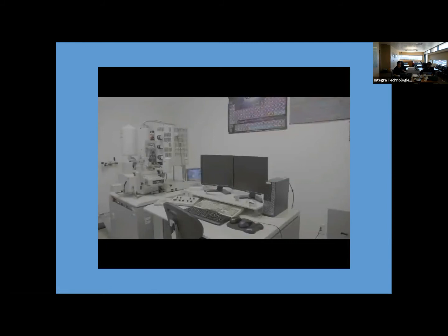It gives a couple of etches if you're looking for aluminum metallization. That's to look at glassivation to make sure the glassivation's intact. You really need to pull out the books to get the glassivation removal techniques. It could be chemical, you could use plasma, you can use argon as a gas for plasma, you could use other gases for plasma. For typical DPA, it is a chemical glassivation removal that happens. But for failure analysis purposes, there are other techniques that we use.